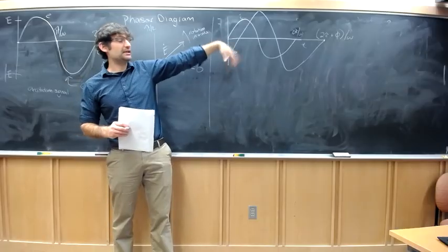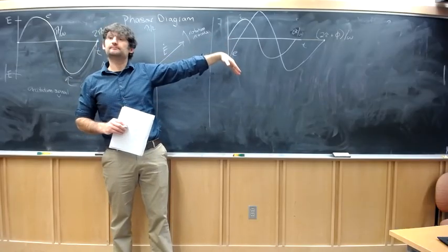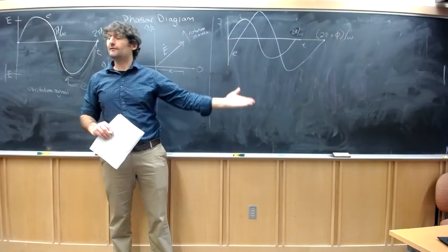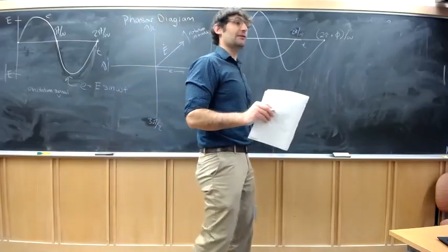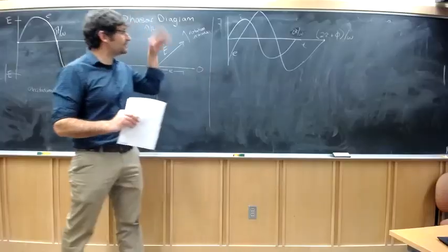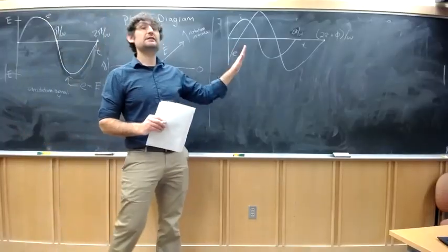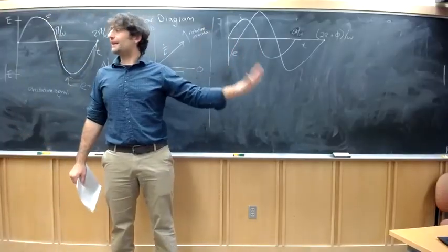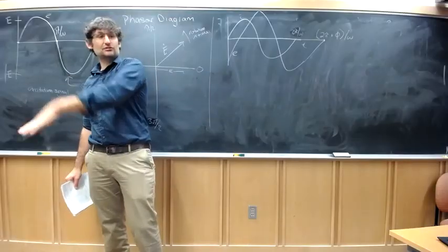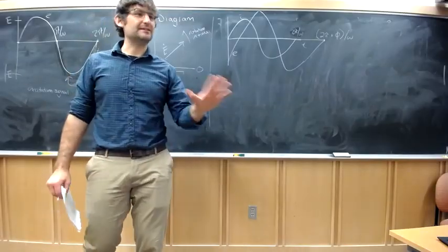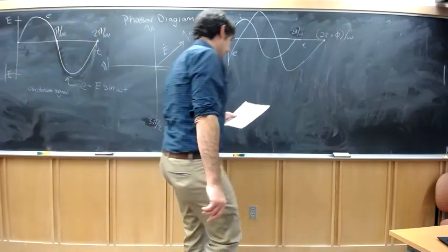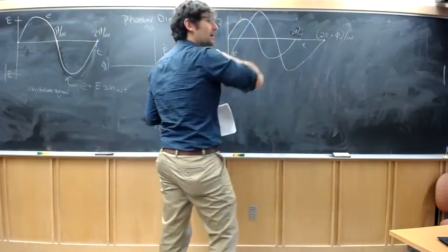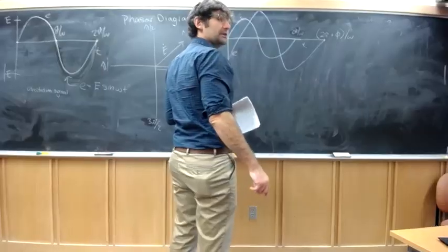Do the amplitudes have to be the same? No, because they have different units. Obviously, there's no reason for the amplitude of the current and the amplitude of the voltage, in whatever unit you happen to choose, to be the same. So they can have different amplitudes. Are the frequencies going to be the same? Generally, yes, right? Because you have an excitation source here. It turns out you get harmonics and things like that, which we won't talk about at all in this course. But in general, yes, this would be the first harmonic response of the curve.